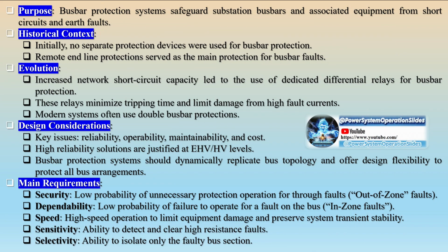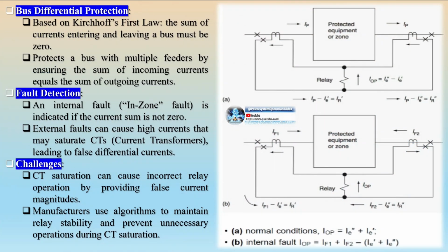Busbar differential protection configuration can be categorized into two main types, one centralized and second decentralized arrangements. Centralized arrangement. Numerical centralized busbar protection is typically found in new substations or in retrofitted old conventional busbar protection systems where the cabling is still in good condition. The amount of cabling in a centralized arrangement is approximately the same as in conventional arrangements. Advantages of a centralized arrangement include easy adoption of functionality and simple arrangements of inputs-outputs. It allows for fast and easy connection with substation automation systems, which facilitates quick fault analysis and monitoring.